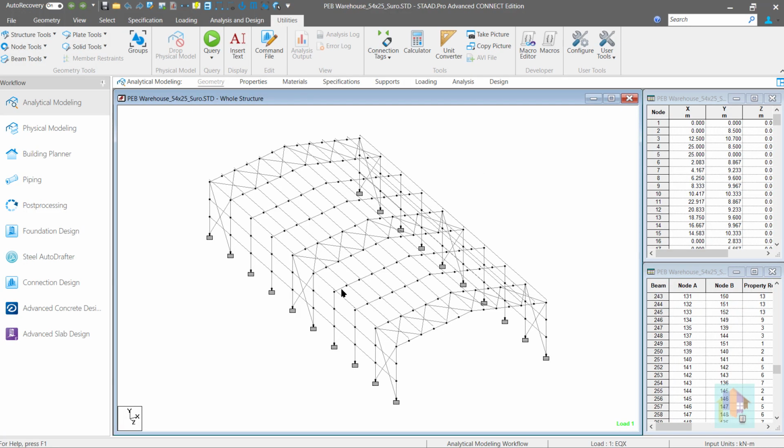First, I want to create a group with tapered rafter and column members. There are several design parameters which are required for a built-up section. Also, we need to filter the results of these members for manual optimization. So this member group will be handy.